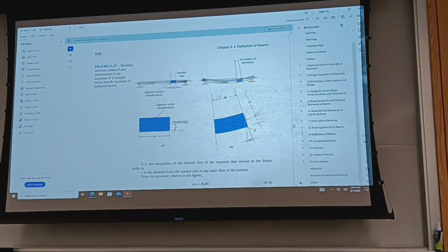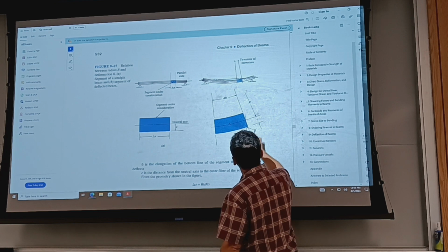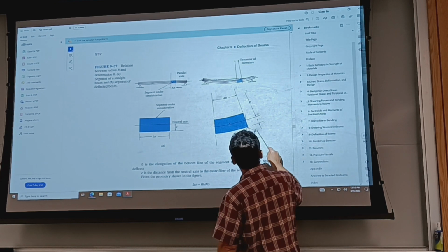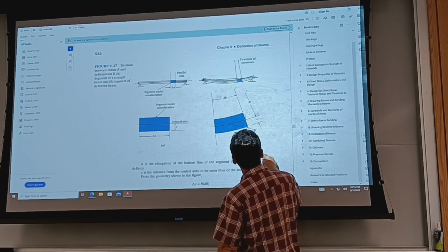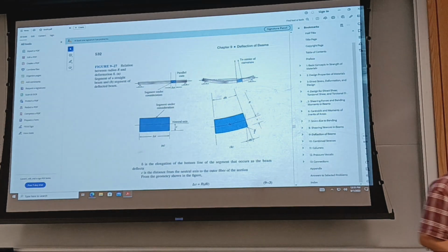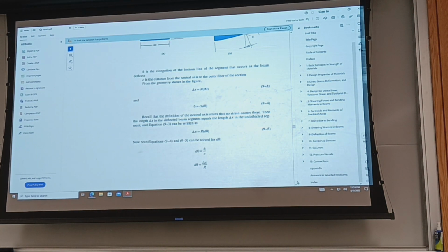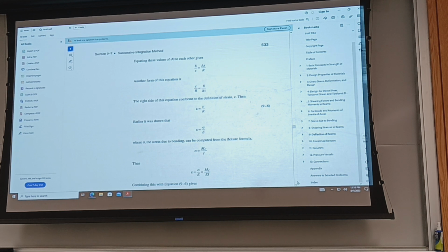Again, the equation for the radius of curvature, the flexure formula, and some geometry. So this deflection delta, the stretch of this beam, which equals the compression here if c equals c, is equal to c times d theta. This little piece is c times d theta. The flexure formula was brought in at some point, along with the definitions of stress and strain, Hooke's law.